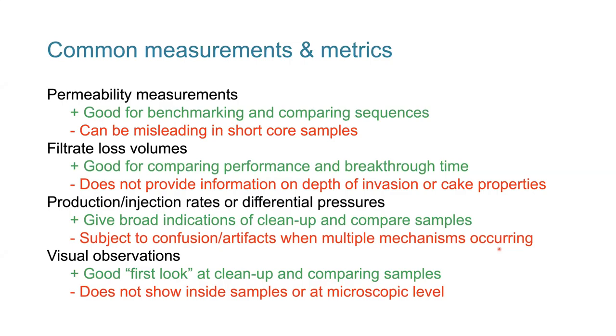But we have to take it with a pinch of salt and be very careful with how far we take the interpretation of permeability. One of the compromises related to the core that we retrieve from the reservoir is that we tend to only have short core samples available for these kinds of simulations, as I said, up to a few centimeters long. So there's a high potential that, for example, drilling mud invasion of solids goes all the way through the length of the sample, and that reduces the permeability significantly. At the same time, during production, we remove clay fines or have some sanding, and that improves the permeability by a roughly equal amount.